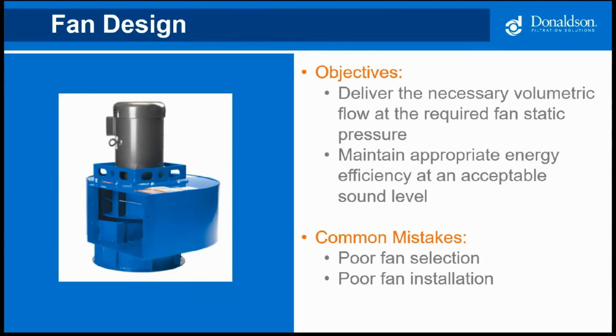So, for example, non-material handling fans located on the clean side of a collector are more efficient than a material handling fan on the dirty side of the collector. Fan challenges generally fall into two categories: a poor fan selection or a poor fan installation.